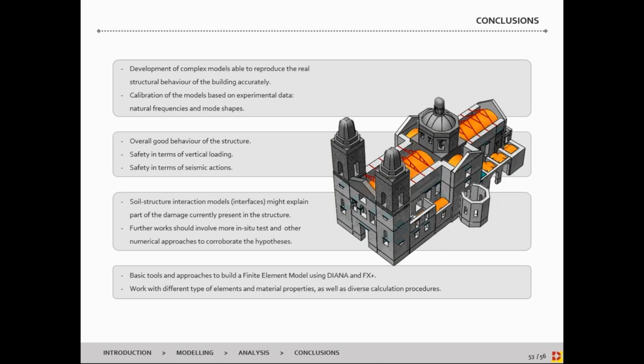So in our particular case for the church, further work could benefit from additional tests in situ, most of all regarding the soil-structure interaction. Numerically, we could also include other approaches such as time-dependent dynamic analysis, or different approaches for the considerations of the adjacent parts or of the interaction between soil and structure.